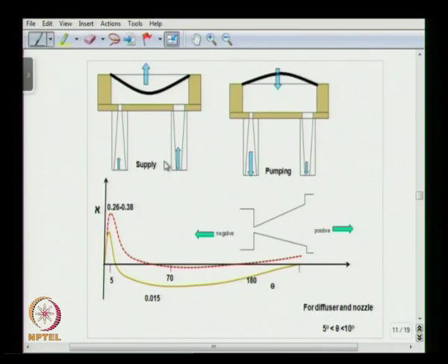Let's continue our discussion on micropump. So we will start talking about valveless micropump. Valveless micropump will not use any valves. They will require nozzle diffuser arrangements to selectively transport fluid from the inlet to outlet by utilizing the difference between the pressure drop that happens across a nozzle to that across a diffuser. So this is a configuration of a valveless micropump that you see here,